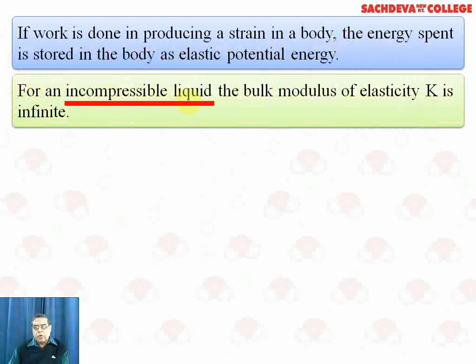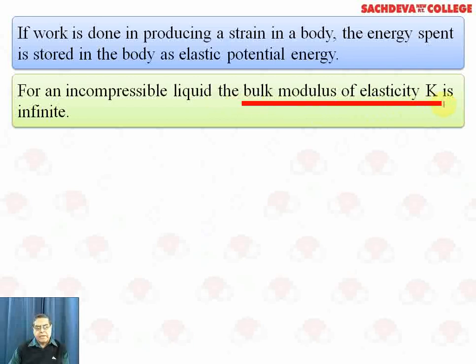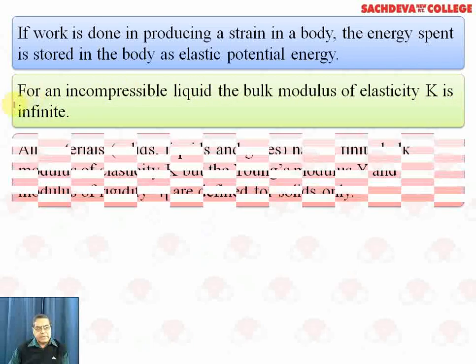For an incompressible liquid, well, before proceeding forward, you can remember that there is no liquid which is totally incompressible. Every liquid gets slightly compressed. So it is a case of assumption. That is, for an incompressible liquid, the bulk modulus of elasticity K is infinite when we press it.